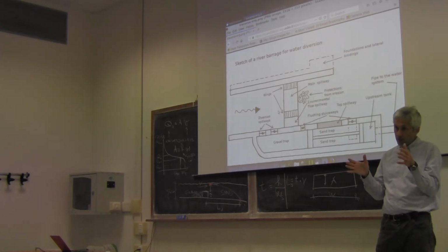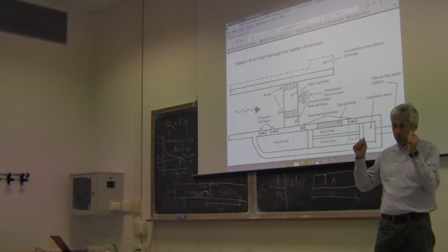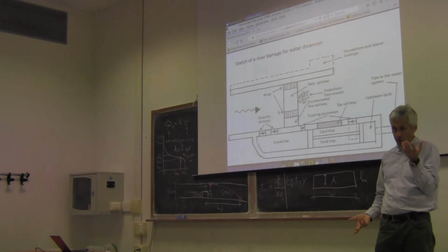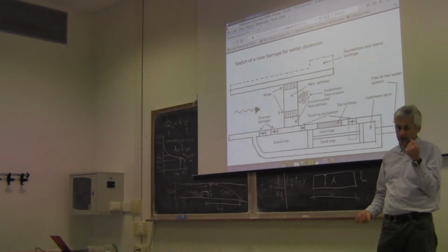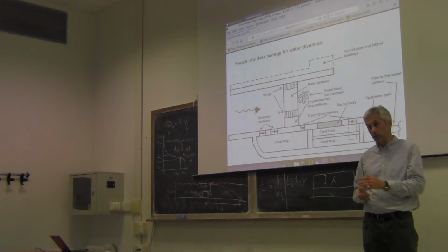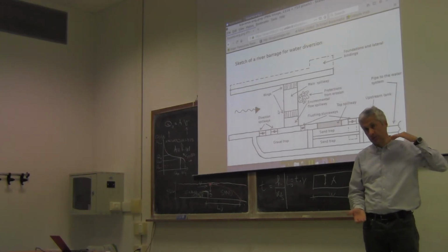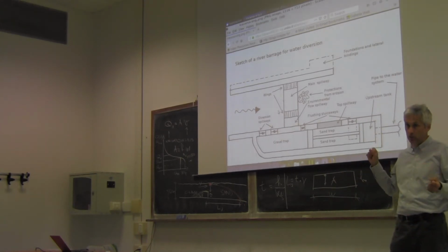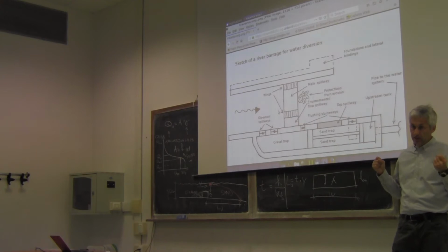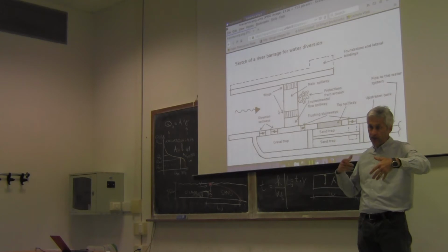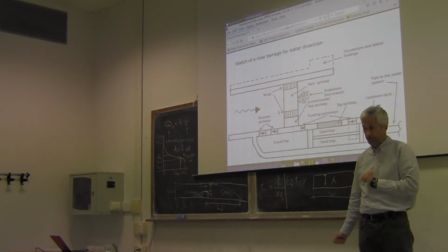But even for hydropower production, very often, water is brought downstream in order to gain head difference in elevation, because you know that the produced energy is proportional to the head, to the jump, and therefore in order to increase this jump, water is brought downstream typically through pipes in order to keep the energy, and then it's routed downstream by placing the turbine at a lower elevation.